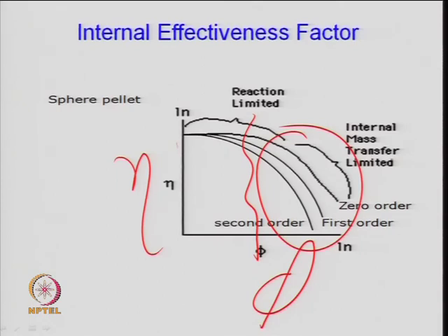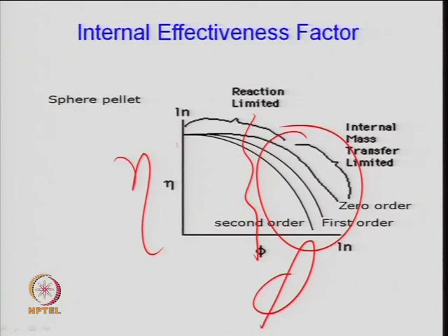Also if you look here, you can interpret that when the order of reaction is increasing, the dominance of diffusion resistance increases, because I told you phi is r under root k Cs to the power n minus 1. So, for a first order reaction the concentration is not there, but for other cases the concentration dependency will also be there. Because if the concentration is high, then you will see some kind of resistance dominance.